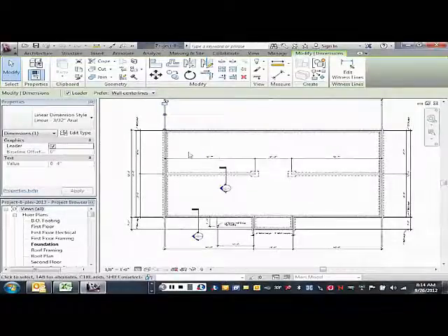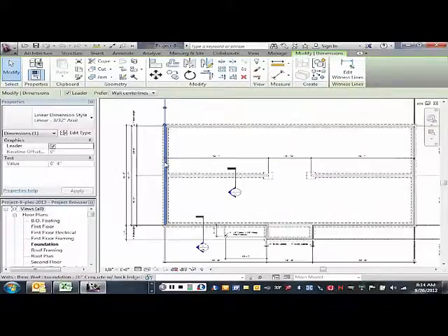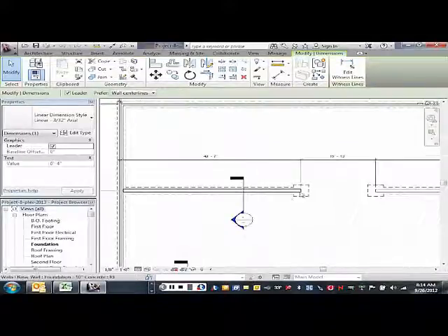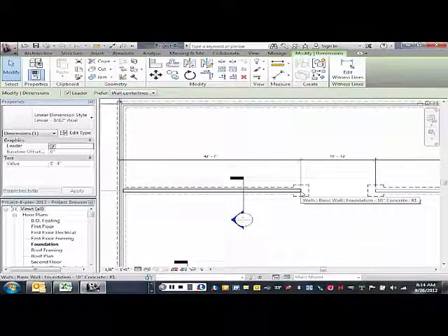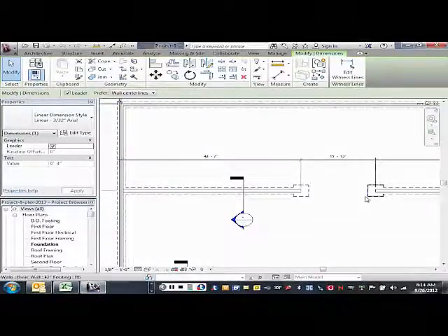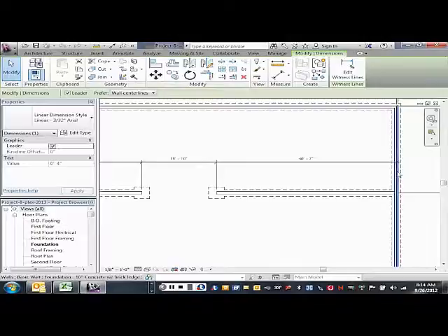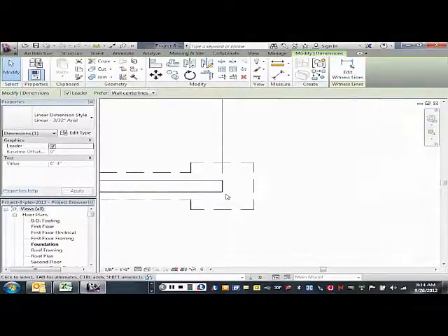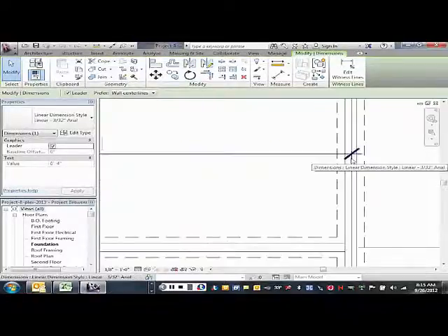And through the middle of the building, again, we have to go from back side of brick ledge, which is the top of foundation, to the end of our wall where the pad footing is, to the opposite pad footing, and then to the other edge again. The end of that wall is centered on the pad footing. Correct. That's not to the brick ledge, that's tall brick.